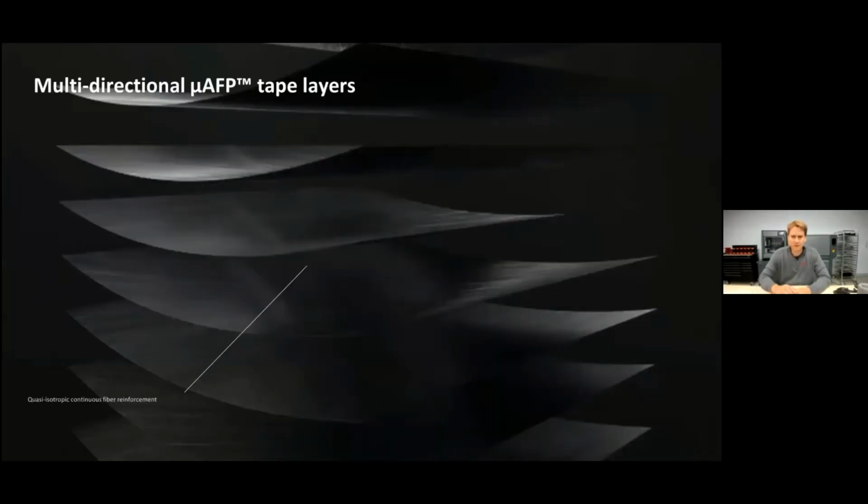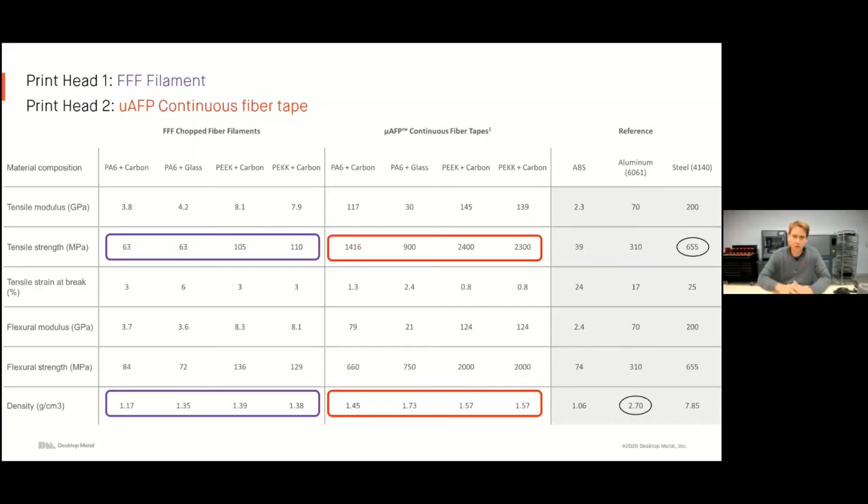So these tapes are made out of these multi-directional fibers that are running constantly throughout the part. There are these wide tapes that we then slit into slits. But these are going to give you an incredible strength. And by altering the direction of these parts, you're going to get a very uniformly strong part that's going to have incredible material properties. So let me now justify to you how we said stronger than steel, lighter than aluminum.